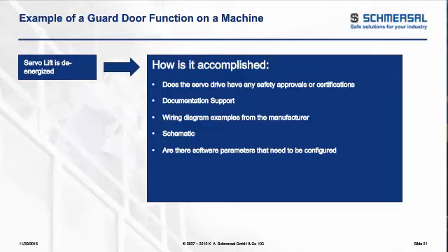You can get a freewheel condition, and you can damage the drive. Definitely things we don't want to happen. So you really need to look at how you safely accomplish shutting down an AC drive or a servo motor or a stepper motor. What's the safe means to meet the safety level the risk analysis requires?